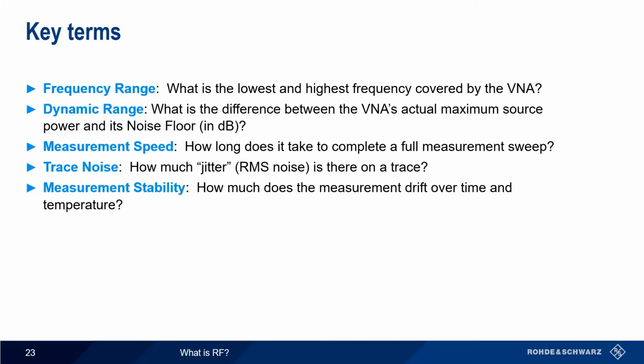Will you be operating the instrument in a climate-controlled environment? The sensitivity of the VNA to temperature changes, combined with performance demands of your application, may drive how often you'll need to perform calibration, hourly, daily, or weekly. Keep in mind that measurement stability is also a function of all the components in your setup, especially cables. Inexpensive or old, worn test cables can have a huge impact on measurement stability and repeatability.